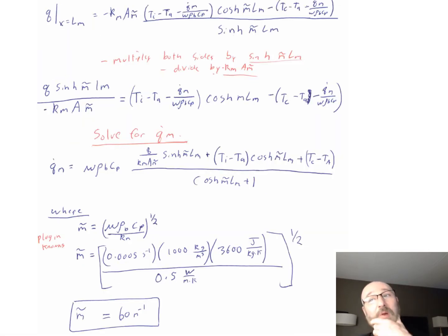So now we keep going, and now you can see how easy it is to get lost in this. So take your time, do this out step by step by step. But this is a very long, involved process and equation. To solve this right here, we can plug back in now for this Q, where x is equal to that thickness, our L sub M, right there, the thickness of the muscle layer. Now start plugging in for our theta sub C and our theta sub I terms right there. We end up with this relationship that we see here.